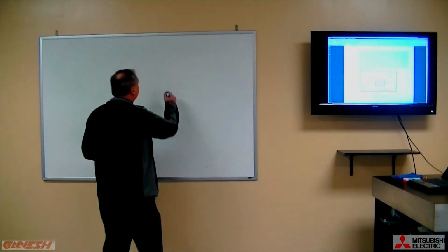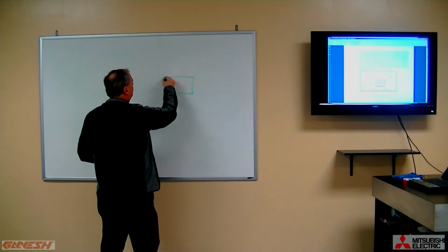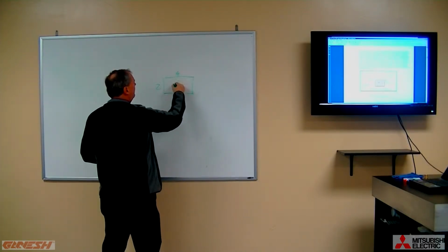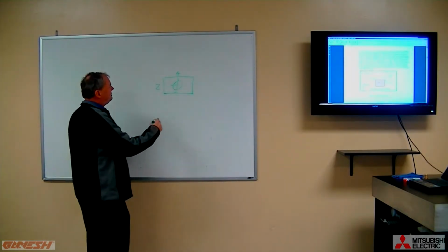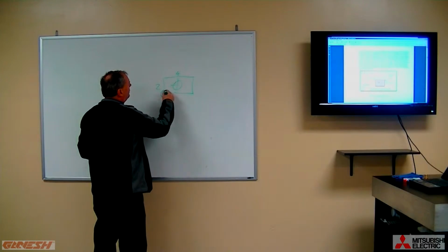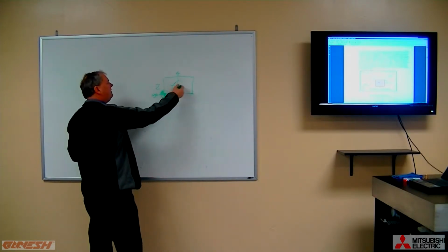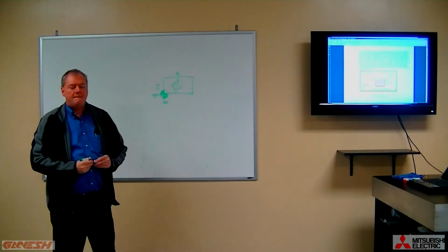So if we're machining a square that's 2 inches by 4 inches, has some kind of hole in the middle, you already know how to do all this. You say, okay, I'm going to pick this corner as my datum, and I'm going to call that x0 and y0, and now everything I do relates to this datum point.